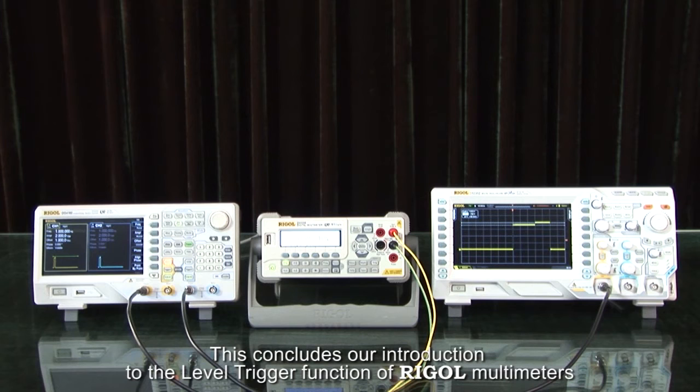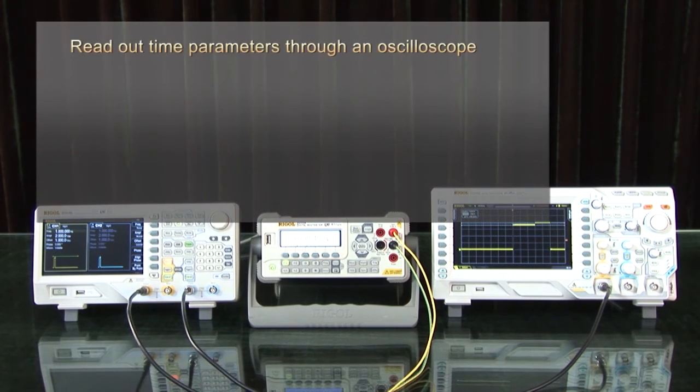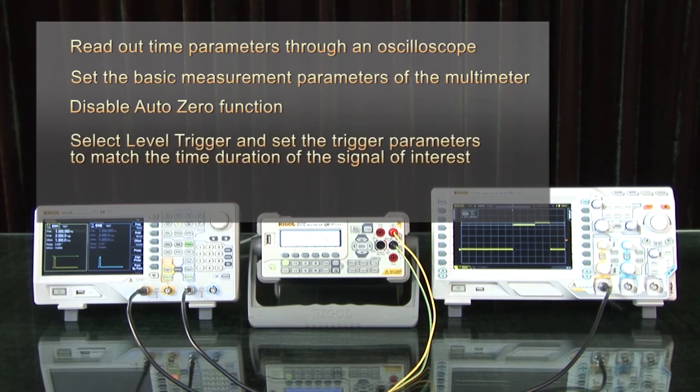This concludes our introduction to the level trigger function of Regal multimeters. The key points are: read out the time parameters through an oscilloscope, set the basic measurement parameters of the multimeter, disable auto zero function, select the trigger level and set the trigger parameters to match the time duration of the signal of interest, and then set the integration time.